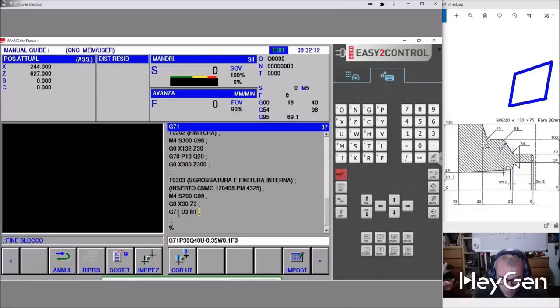Now I'm inserting, so I'm positioning myself at N30 X54. I need to do a 2mm chamfer to the edge of the part, so X60 Z0.